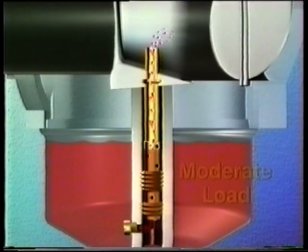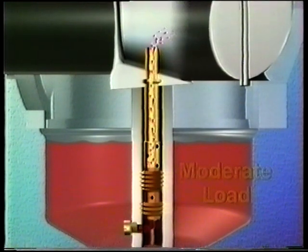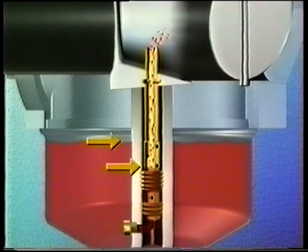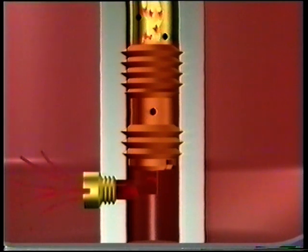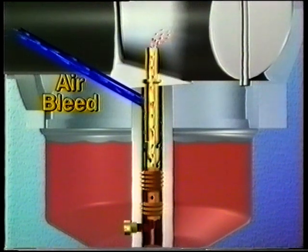When the engine is running under a moderate load, the level in the tube drops even further. At this point, there's a significant difference between the level in the tube and the level in the bowl. Again, the limiting factor is the amount of fuel that can pass through that orifice in a certain amount of time, compared to the amount of fuel the engine is actually consuming. At this point, the high-speed air bleed feature comes into play.